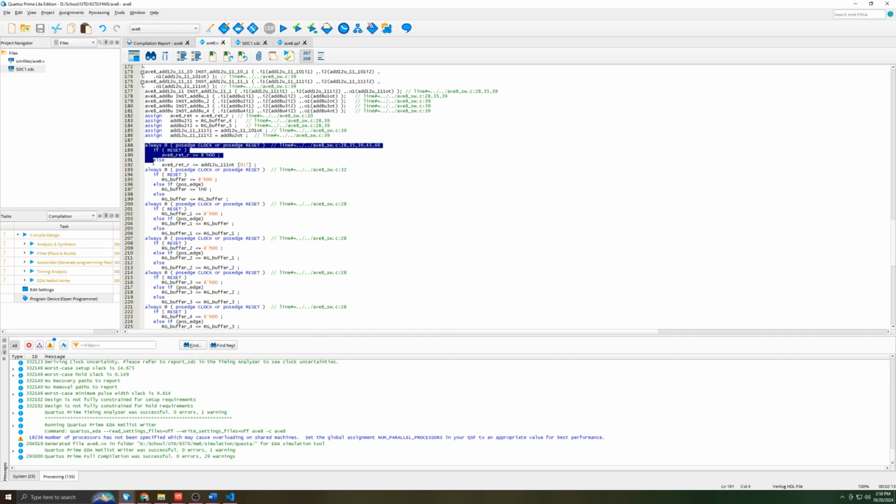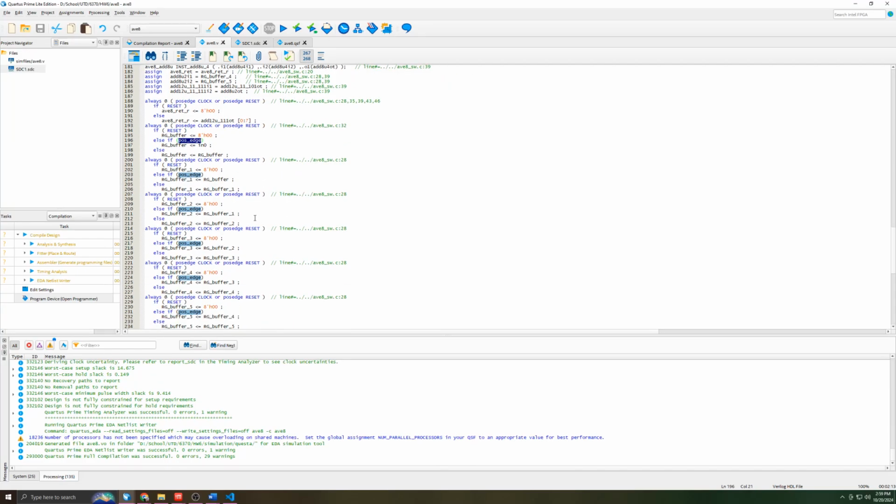I didn't modify the return, but for the shift register, I added that it has to shift on the positive edge signal, and otherwise it retains its value. Like I said before, I could have avoided this by having the positive edge signal act like a clock pulse, but I did not go with that.